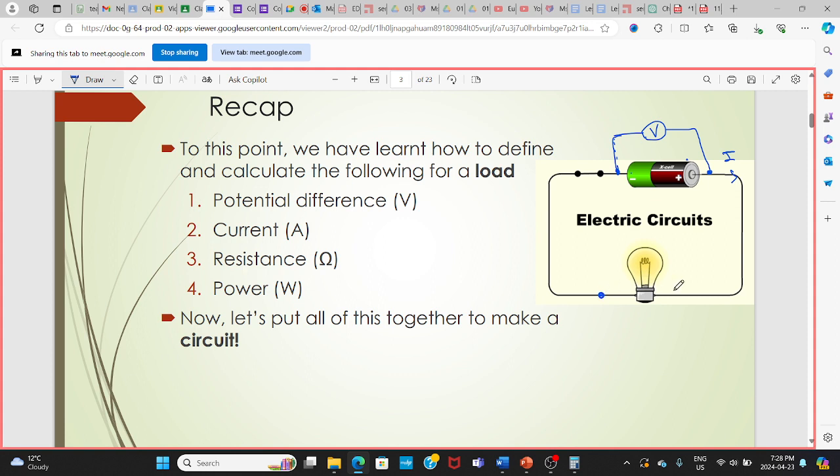Again, if you put your voltmeter across the light bulb, you have to put the voltmeter in parallel. Measure the voltage. That would be the same as the voltage you're measuring across the battery. Why? Because these two points, I call it point one, and I call here point one as well. These two points are the same point.